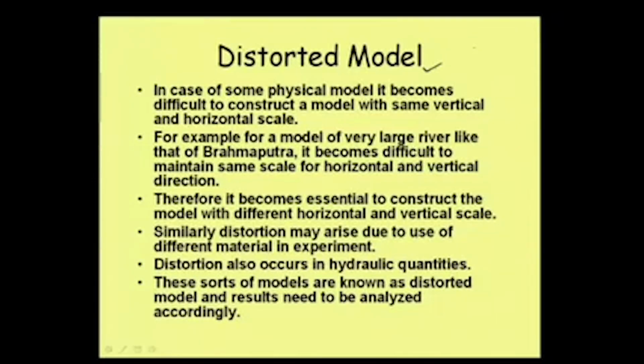But in the model, if we reduce it to a very small depth, then the surface tension force, which is not dominating otherwise, may become a dominating force. So that way we can face problems. Well, let us see what are the problems that we may have and how we can overcome those problems in a distorted model.